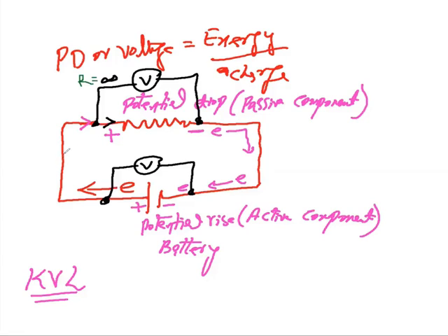Why do we connect the ammeter in series? Because we want to calculate the current, all the current which passes across this ammeter. If we connect the ammeter in series, that is the only way through which we can get the complete current. But if there's a heating effect, would that increase or decrease the voltage result shown on the voltmeter?